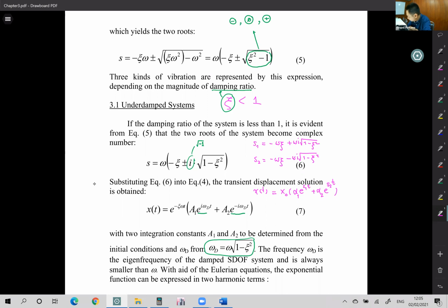I'm sorry I don't have clear information about this, but to me the concrete structure itself contributes very little to the damping ratio. Maybe the foundation gives very high damping. So of the 2-3% that the design code recommends for reinforced concrete buildings, maybe 70-80% is a portion from foundation dissipation.